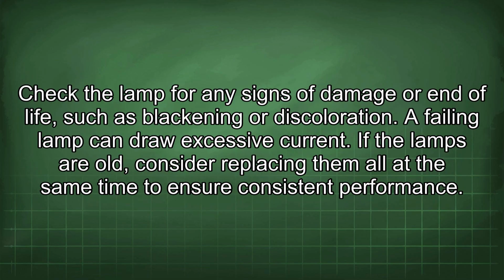Check the lamp for any signs of damage or end of life, such as blackening or discoloration. A failing lamp can draw excessive current. If the lamps are old, consider replacing them all at the same time to ensure consistent performance.